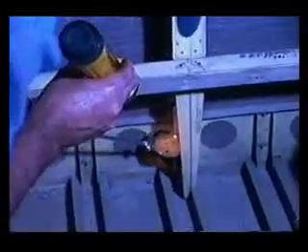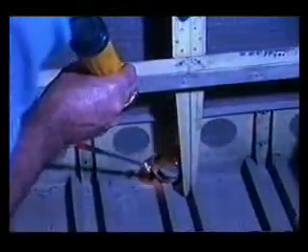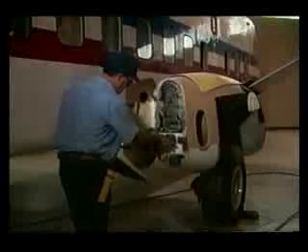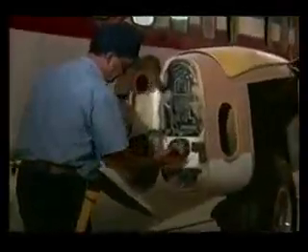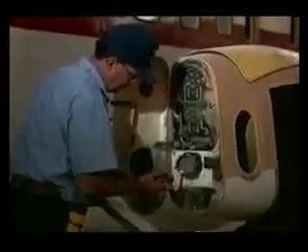Any corrosion found should be written up. The level of corrosion should be defined, and action should be taken. All trouble spots should be kept as clean and as dry as possible. During daily inspections, all drainage paths should be checked and cleared, and standing water should be removed from the aircraft. A well-planned corrosion control and prevention program should cause little disruption of current daily maintenance routines.